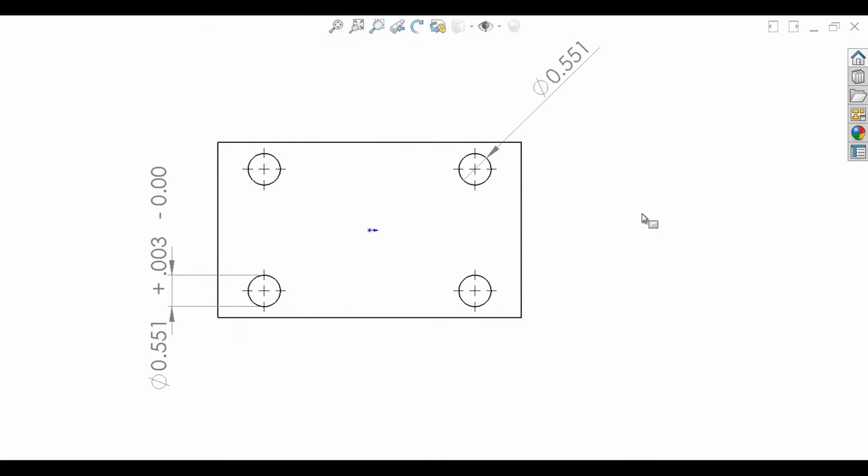So that's one example of where we use the decimal precision to determine how accurate we're taking our measurement. The other thing to understand is that with any sort of measurement, there's always those error bars, the tolerance of the measurement, so to speak, that come into play. Because you can only measure something so accurately, and there's going to be a little bit of fuzziness right at the resolution of your measurement. So everything always has a plus or minus tolerance value on the measurement at its minimum scale.